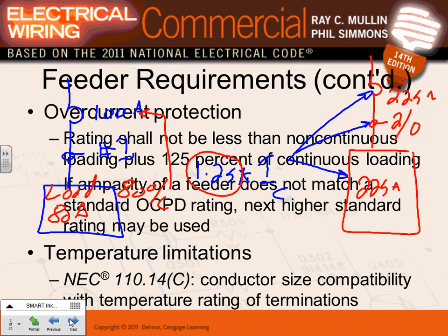So that's basically it. Temperature limitations. There's a temperature limit. You remember we went through this one in detail. I have a couple of pictures. For conductors number 14 through 1, 60-degree column. If the amps are 100 or less, 60-degree column. Everything else, 75-degree column. 90 degrees only for the rating. That's what this is telling you when you size.